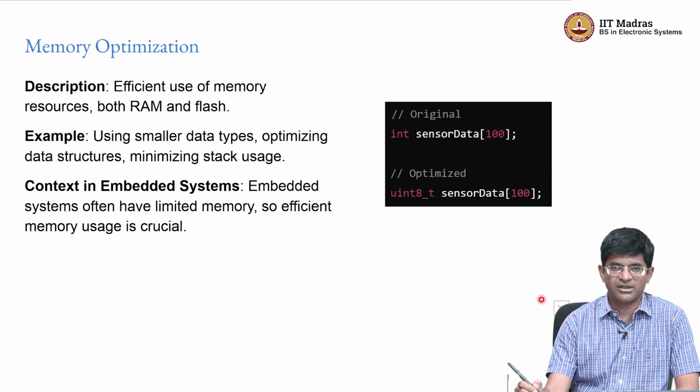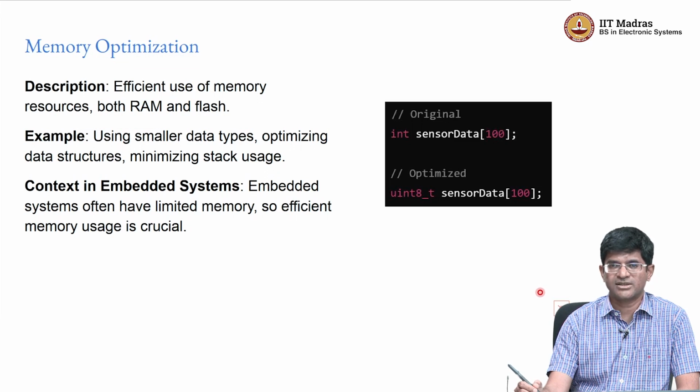Now there are interesting things that happen here, one of which is that even given that flash is a read-write kind of memory, you can both write data into flash as well as read from it. Sometimes there may be a temptation to just take the data that you are receiving and store it into flash straight away. And it turns out that from an energy point of view, that's probably a bad idea, because writing something into flash memory is going to consume significantly more energy than having something which is just written into local RAM. Another thing which is kind of interesting is that depending on how you choose your data structures, you might end up being able to have your entire data structure stored in cache memory for the duration of your computation.